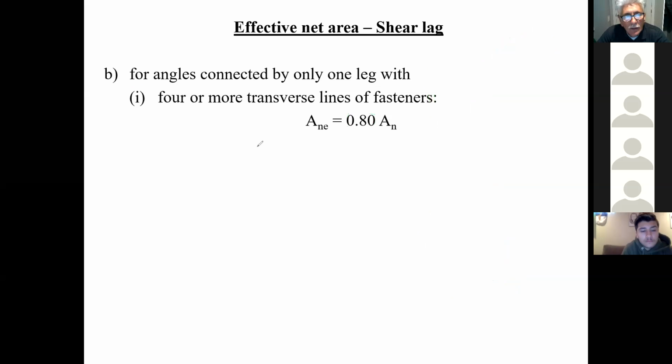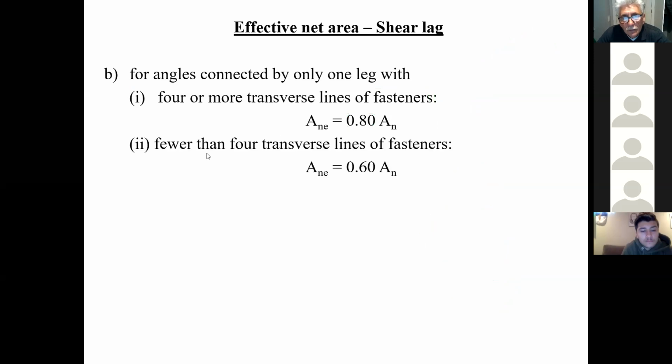Sir? Yes. And that net area is just on the face that the fasteners are on, right? No, the net area is the net area across where you're calculating the resistance for your connection, and we'll get into that. Remember what we did for the plate when we were doing the tension, when we were doing the connections the first time? I'll talk about the net area.